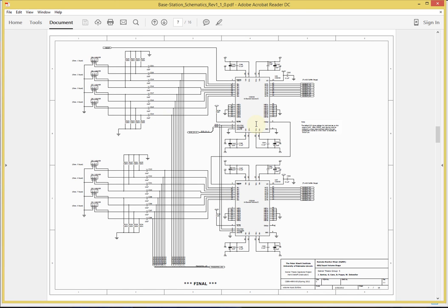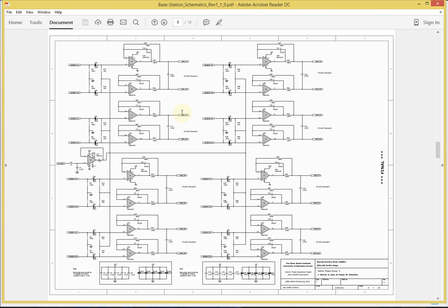It is fragmented in the context of subsystems and hierarchies, but the circuit is completely all wired up. So I can follow the eye and see where the lines are connected to other lines. If I just drop symbols and just use net labels everywhere, this would be a nightmare to understand, but also to debug. You waste time if you're debugging a circuit because you keep constantly having to search for information that is not there. Again, analog block, so signals coming from the left and the output on the right, and the use of symmetry and clarity.